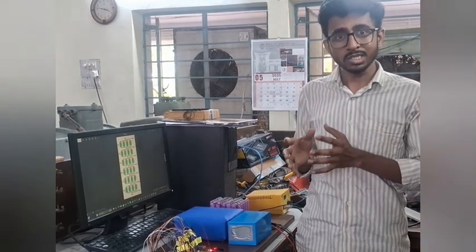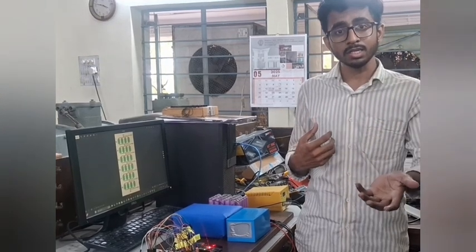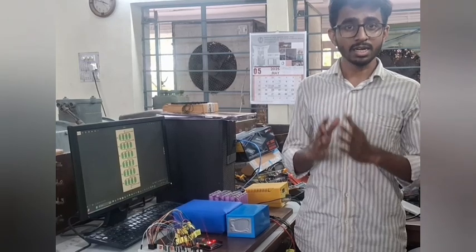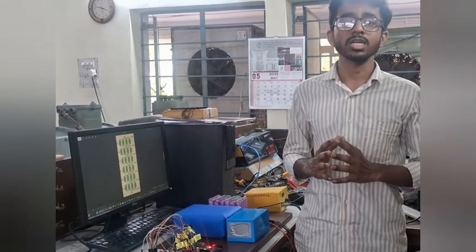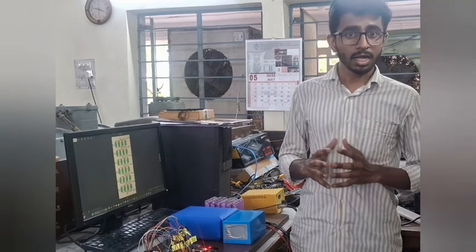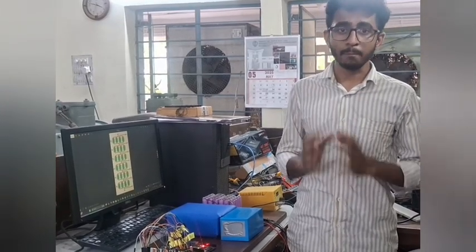On the same side, what is happening? This weak cell itself is extracting the electric charge from the other cells. That's why it is getting heated. So there is a chance or a probability that this weak cell might enter the stage of thermal runaway. If this problem is not addressed early, then the overall rating and the capacity of the battery pack will be impacted. The identification of this weak cell is a very great challenge.